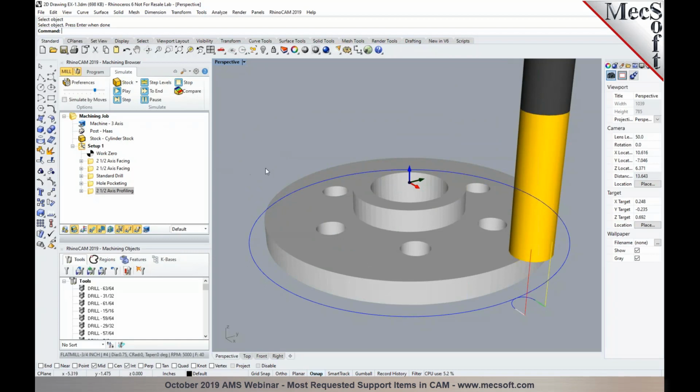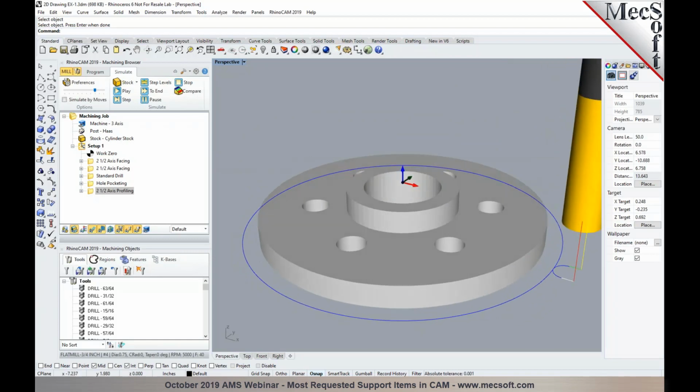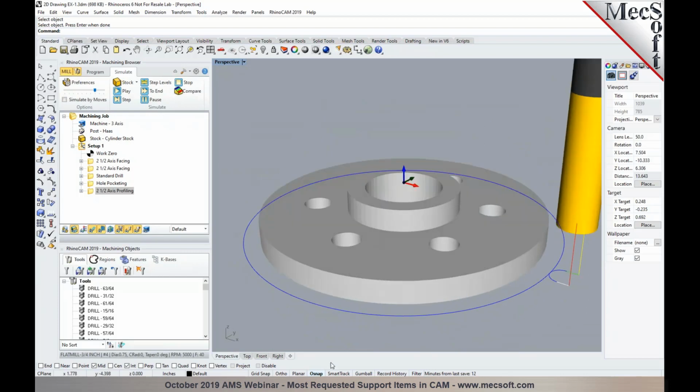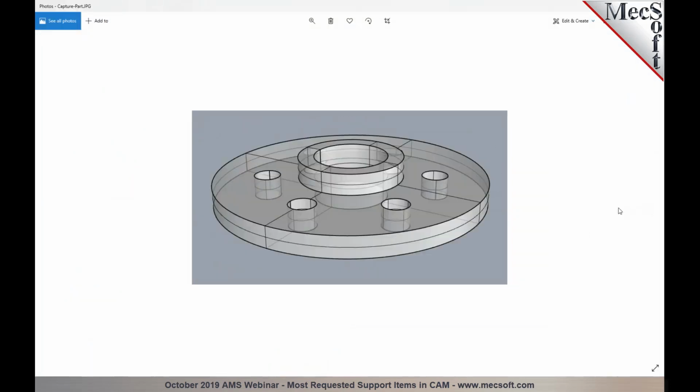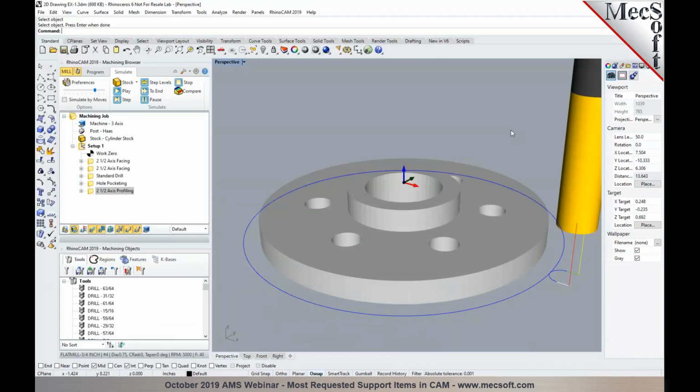So folks, you can see here, from just a 2D drawing, you were able to program this part to achieve the exact result of the finished part that was modeled in 3D, even though you were supplied with just a 2D drawing. So by using the location of cut geometry, or cut depth control, you can accomplish these results without having to have a 3D part model.